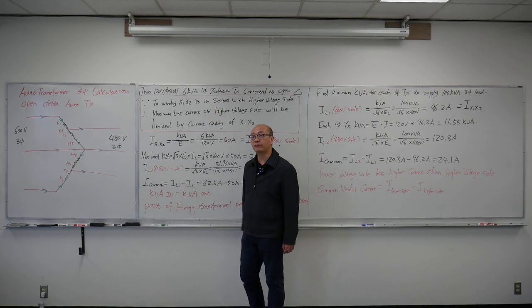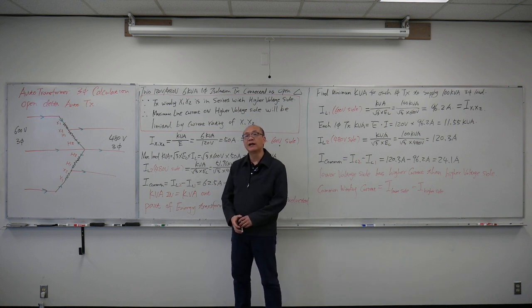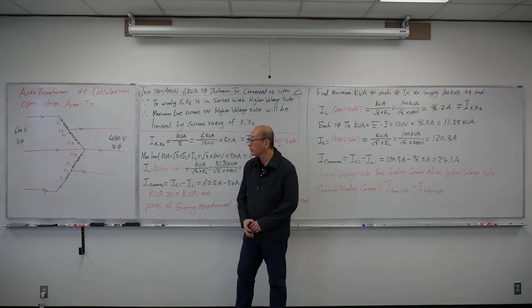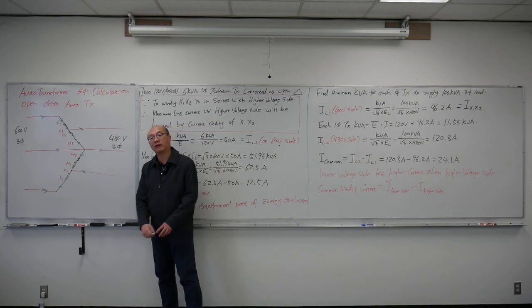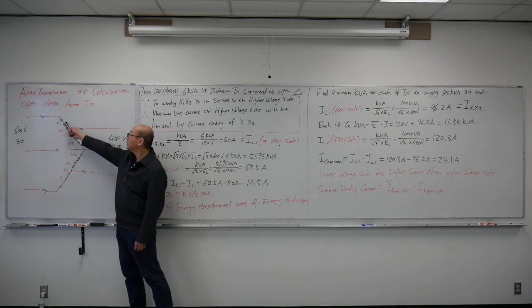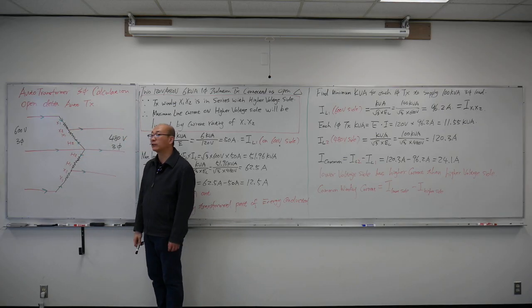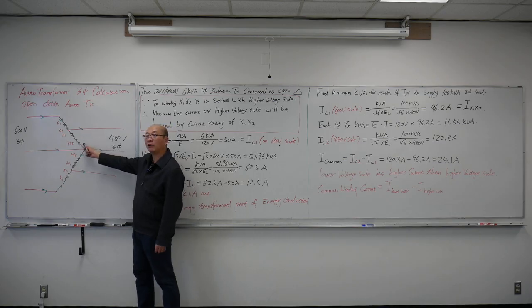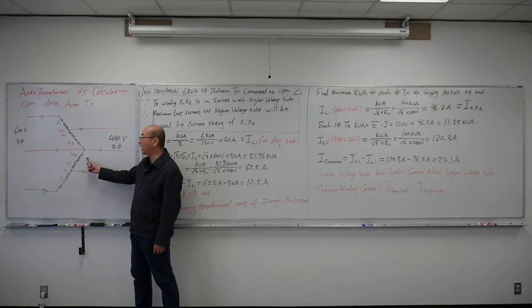I connect those single-phase isolation transformers as auto transformers, and I use two of them to make the open delta connection. So here's a picture. I like to draw those open delta auto transformers. I connect X1, X2, H1, H2 of one transformer together as one of the open delta auto transformers. Then I connect another one the same way.